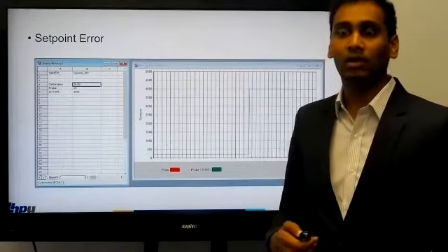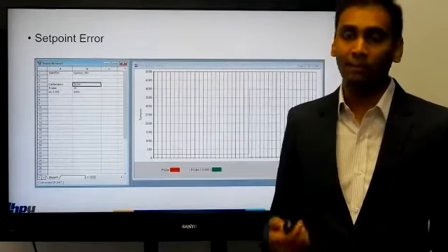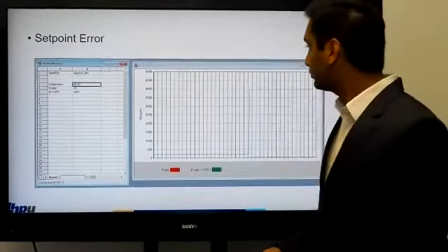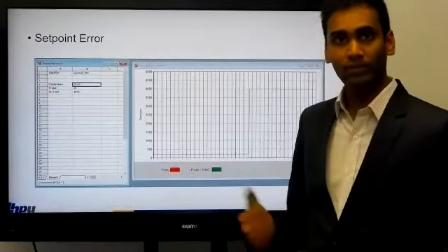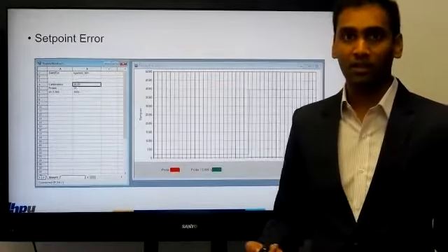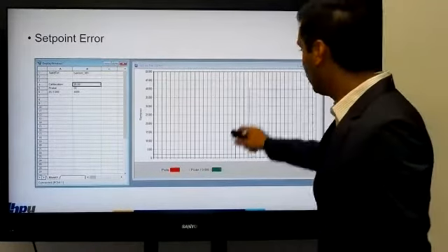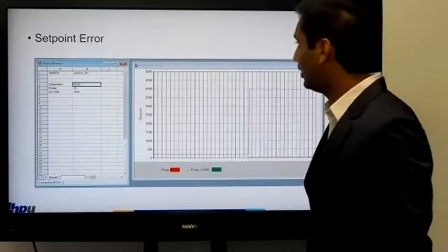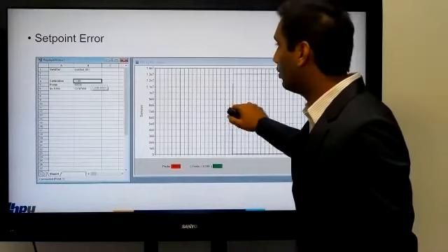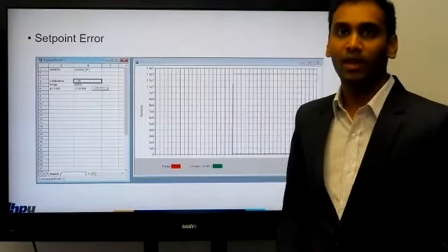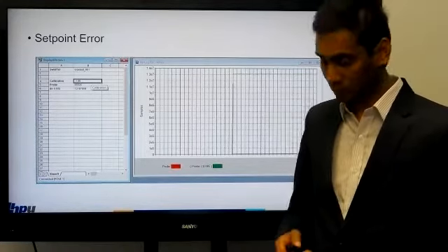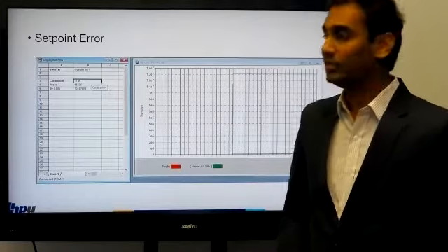We then concluded that that was the process going on in the embedded C code when we convert our simulating model into the ECM. So when we had an input of 20 for the conversion block, it was working fine. Since it's a time step of 5 milliseconds, we got a value of 4,000, which is perfectly fine in this case. And then we had an input of -1. This time we got a value of 65,535. And then divided by a time step of 5 milliseconds, you get 13 million, which had been causing all the problems. So this is the end of my presentation.